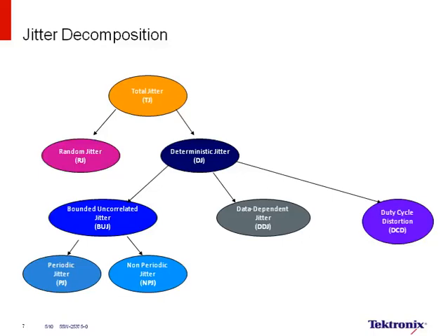Let's look at the other leg of the TJ, and that's DJ or deterministic jitter. The biggest root cause there is the channel or bandwidth limitations in the channel. So if you want to look at improving the DJ, one clear example would be to increase the overall bandwidth performance of your channel, because the ISI or the bandwidth restriction of the channel is what causes the DJ phenomenon.